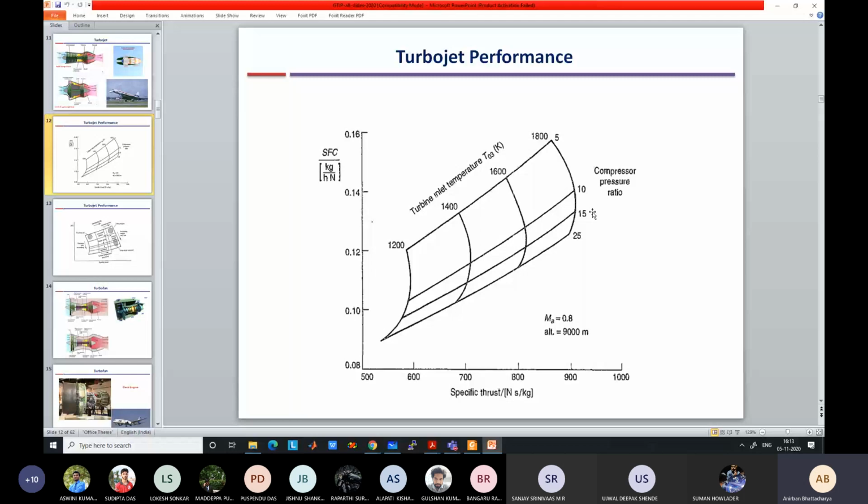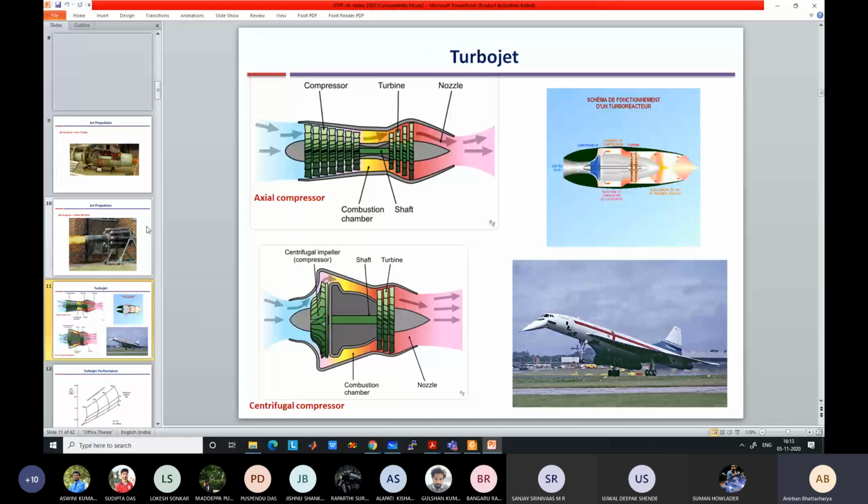Just assume that for turbojet you get better characteristics, better performance, even for the internal part also, better energy conversion at very high velocity or very high pressure ratio. For turbofan, for overall lower pressure ratio, you get better energy conversion. But the question was a very valid one.